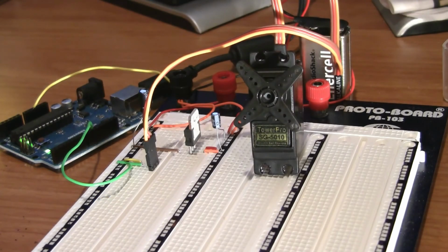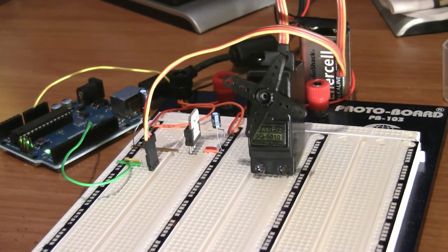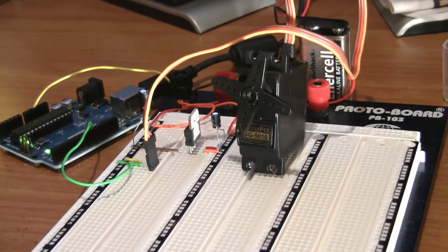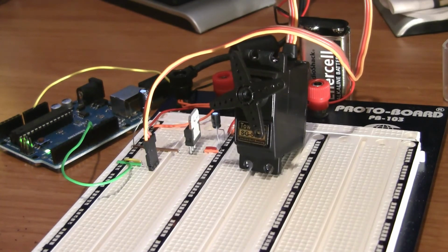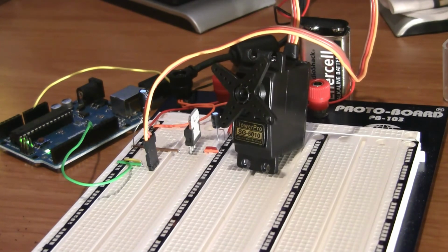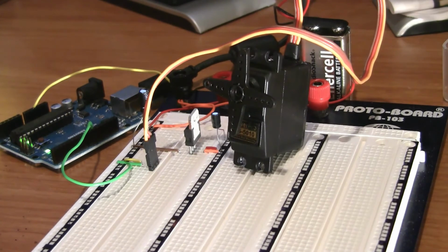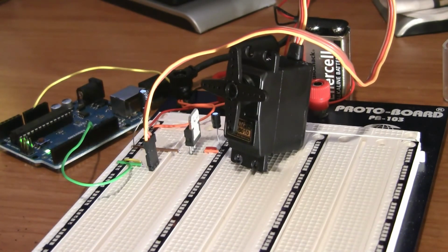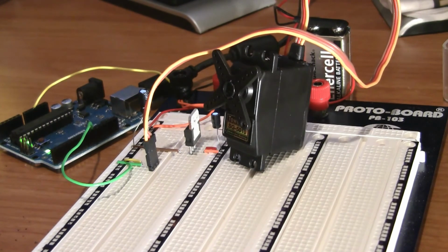Okay, so we can see that every 1 second, the servo rotates by 20 degrees, just like we asked it to. And when it's done, it automatically rotates back to 0. It's able to determine automatically what its range is and what direction to rotate in to get back to whatever position you tell it to. And it's just that simple. In fact, we can actually see that the servo is kind of walking along our breadboard a little bit here.